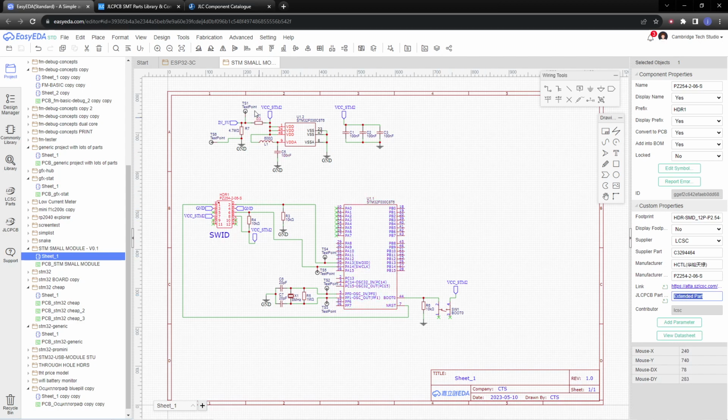When you're working on a design, it's useful to keep checking that you've not made a mistake. It's very easy to just inadvertently pull in a resistor or a capacitor that's not basic, and you're going to pay another $3. You imagine that every component here, I could easily choose a part that's extended. 20 parts could add $60 to the price for no real reason.